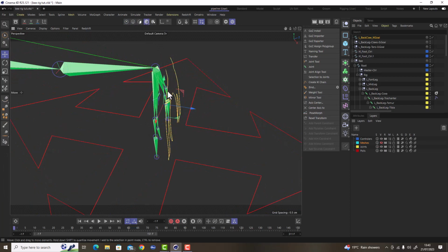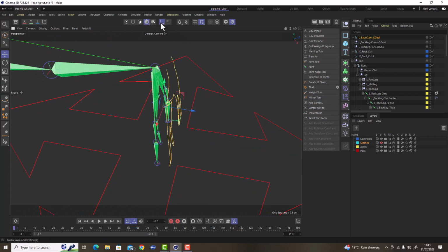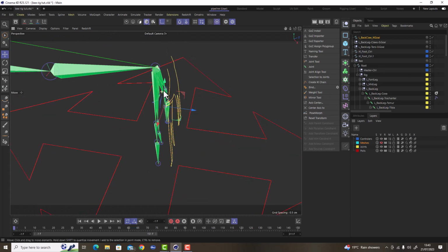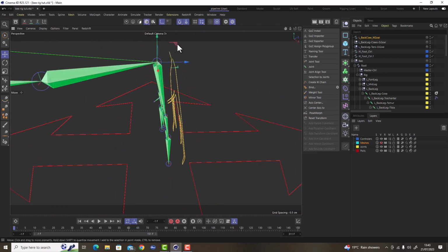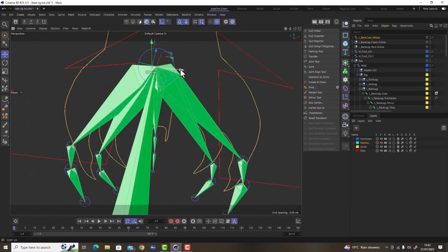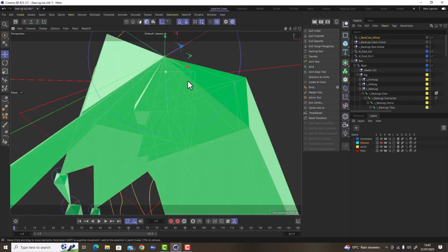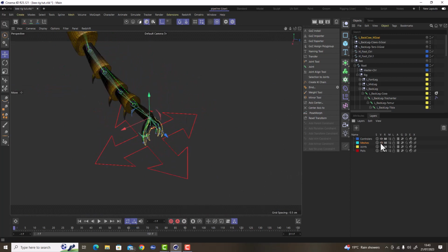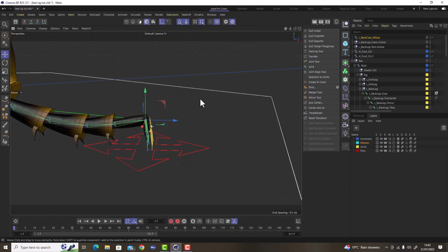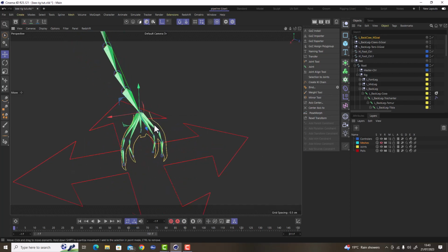Now what I want to do is I want to move the axis to where it should be for the foot. So we enable the axis center again, and we're going to use our snapping tools, and because it's already centered where it should be, it's easier just to move it up and snap it to its correct destination. Just slightly off there. I'm just going to tweak it until it's on there, and I'm happy with that. That's great. It's good to turn on your mesh every now and again as well when you're doing this, to make sure that nothing's misaligned, like the joints haven't shifted away from where the mesh is. So this is a really good position to be in.